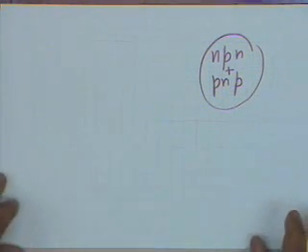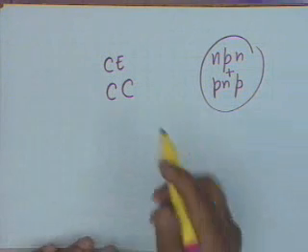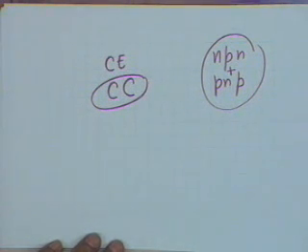Let me draw the circuit first, then I will explain. The circuit uses what is known as, well, you have known the common emitter amplifier. The circuit uses common collector stages, that is, each of these stages, NPN and PNP, which are connected in a push-pull configuration, instead of CE, they are CC. That means the collector is common between input and output.